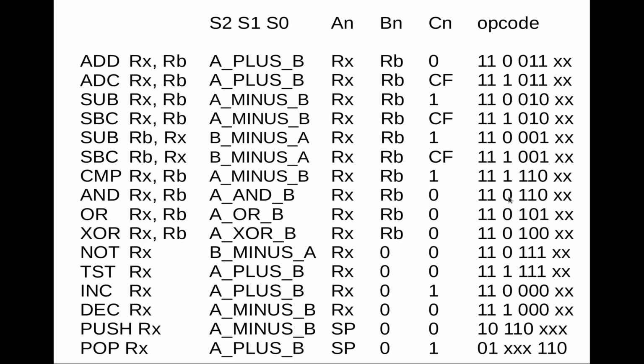And so in this case, for example, I'm once again hijacking one of these opcodes which we don't use for its official meaning, and assigning it a totally different meaning. So I'm using this AND operation to actually mean compare. These 3 bits, in fact, correspond to this AND operation, but that doesn't matter. This is just an opcode. I'm just finding some space for this compare instruction somewhere in the opcode space.